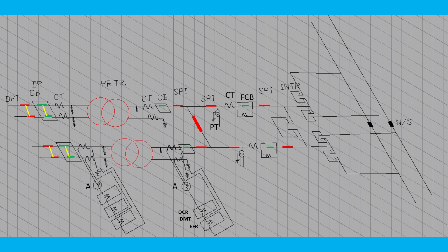And also for the transformer protection, some relays are there like pressure relief device and oil temperature indicator. These are all mechanical relays associated with electrical relays also, for protecting the power transformer because it is hugely costly and may cause a fire accident if you don't protect it.